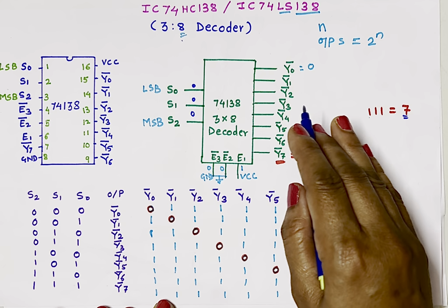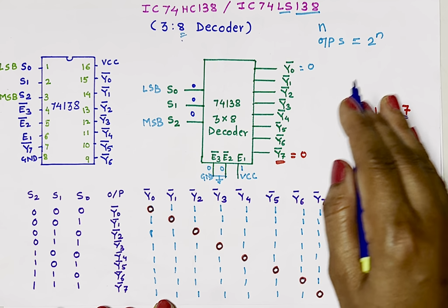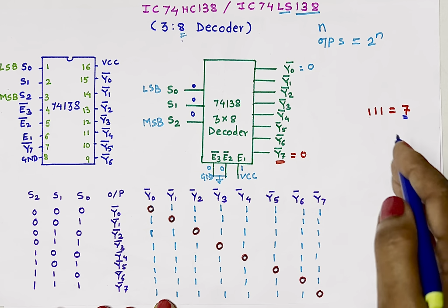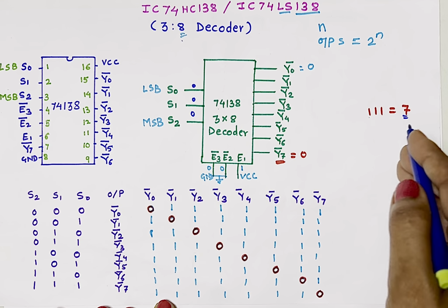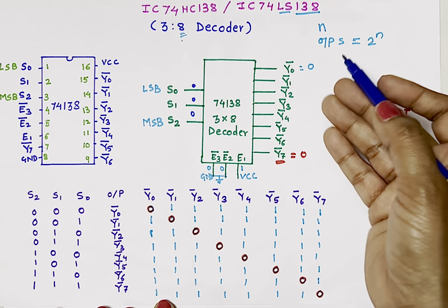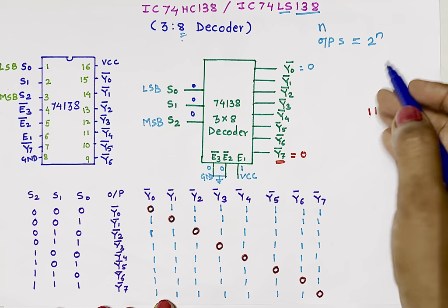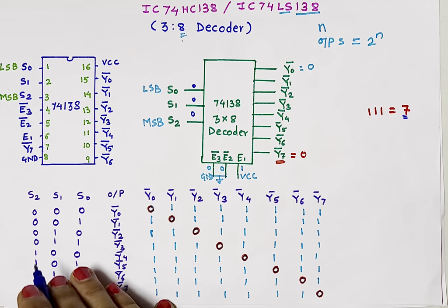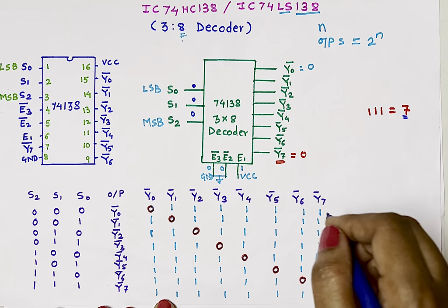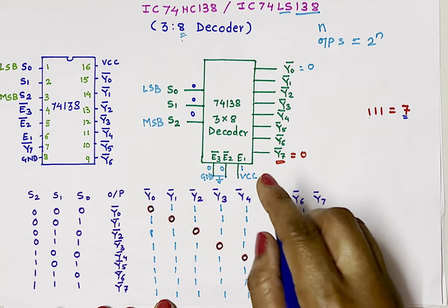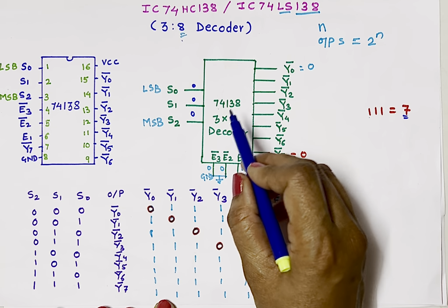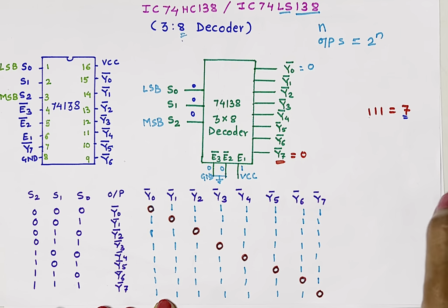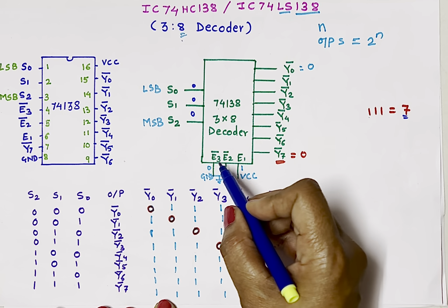So here I have chosen IC74138 which is with active low because in many universities I have checked the syllabus and this topic is used for practical implementation so that it will be easy for you to implement. If in the exam only part 2 is asked, then you can describe what a decoder is, which has select inputs and which has outputs. Then it has 3 enables.